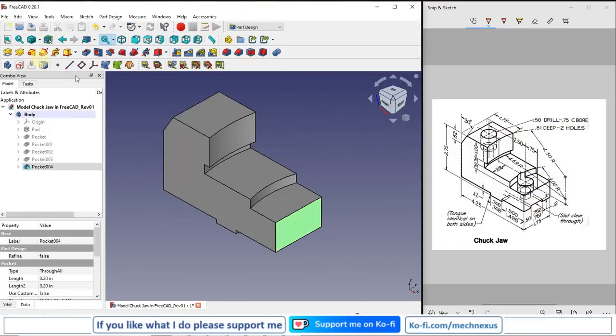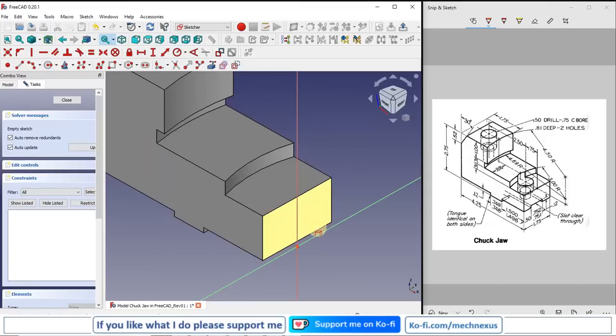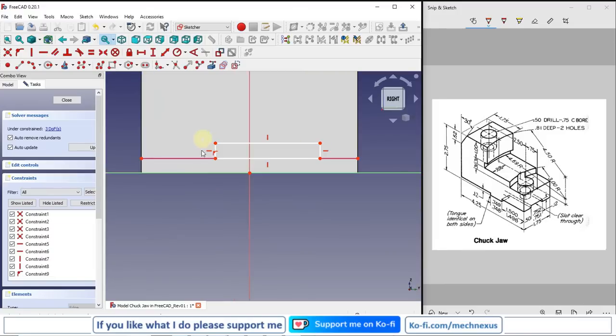So I will select this face and I will say sketch, and I will go for the isometric, and I will project my edge, and here I will draw a rectangle, and I will make these 2 points symmetric. So I will select this one and I will make symmetric,